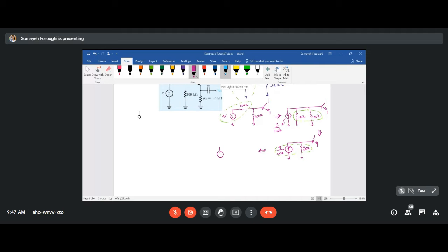You know that the current will pass through this resistance, so it will be the current times the given resistance, that is 5 over 100K times that resistance. Then you will have the equivalent resistance in series connection, and then the transistor and the rest. Finally, by doing this, you can find that voltage source to become 2.5 volts.